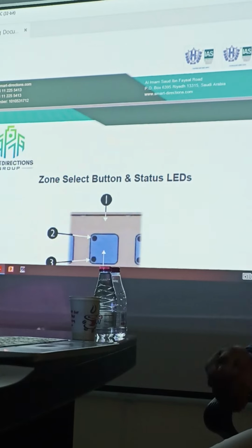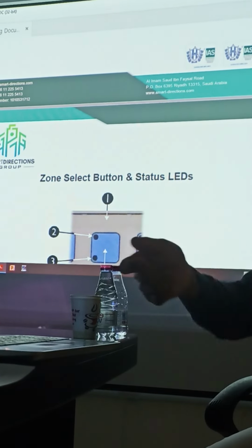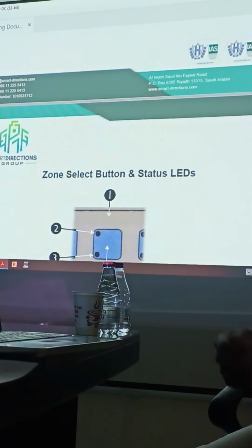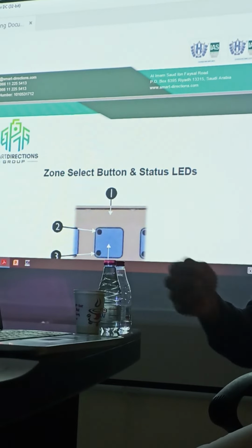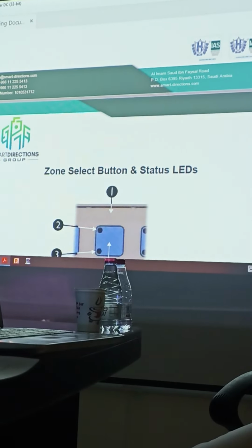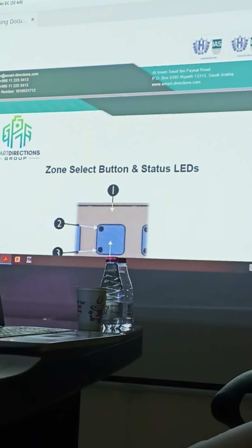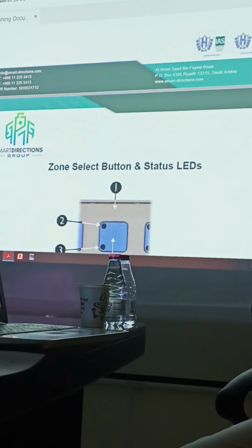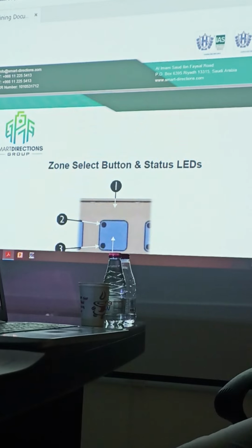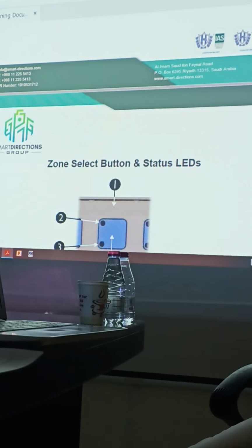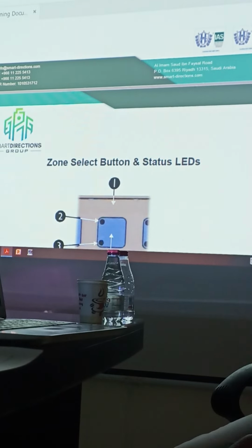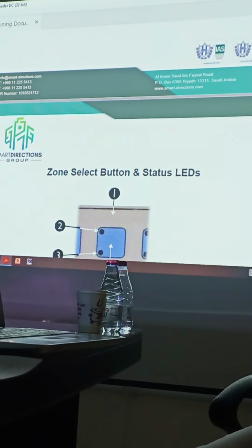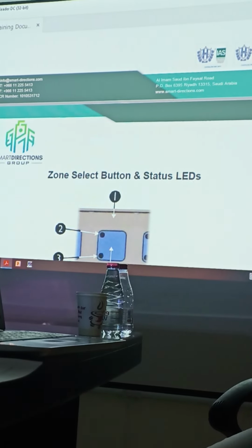The fire system is made with indicators which will tell you that fire is there. Our system is not a fire alarm system. Our system provides communication when there is an emergency. So we are achieving this communication when fire is there. If you want a fire alarm system, there is a system, I think from Honeywell or somebody. When there is a fire, you will get an indicator, a buzzer, flasher, strobe or sounder from the fire alarm system, not from our system. Our system is just taking the command from the fire alarm system as a NO contact, and it provides communication at the time of emergency.